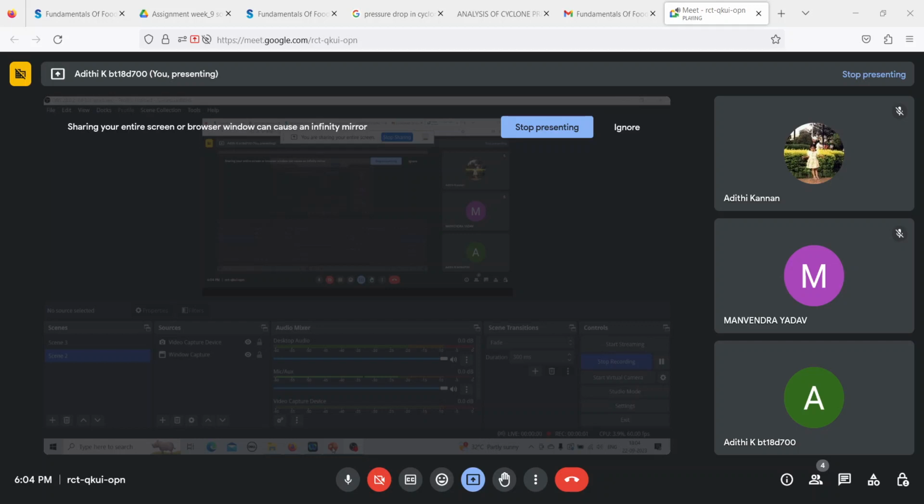The effectiveness of a screen can be measured by two different techniques. One is the screen efficiency and the other one is known as the capacity. The screen efficiency is a measure of how closely two materials A and B can be separated, that is, how well you can separate A and B materials. And the other metric, the capacity of a screen, is measured by the mass of the material that can be fed onto the screen per unit time per unit area.